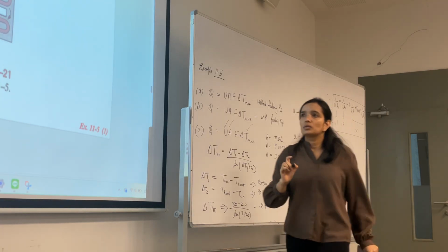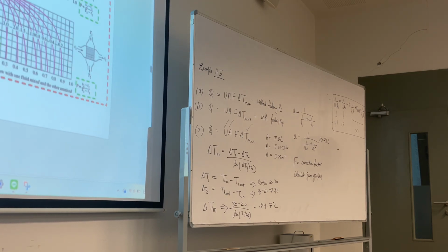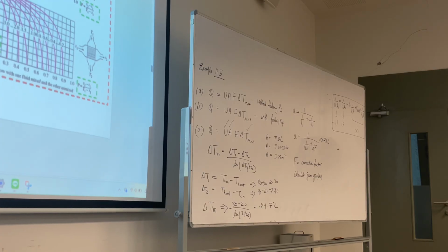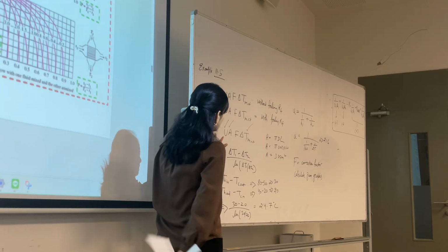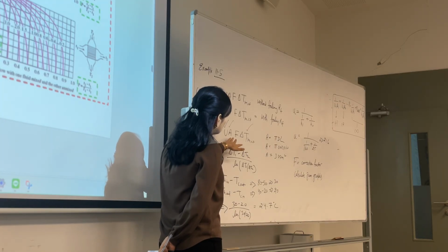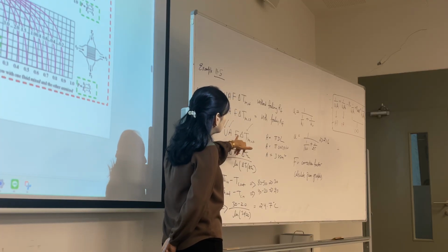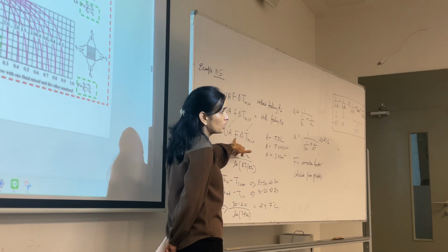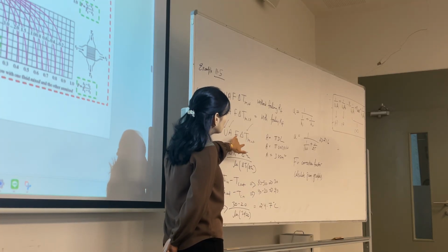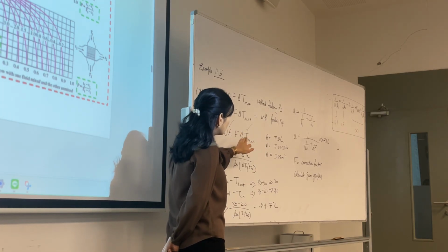How? So this question, example 11.5, is asking heat transfer rate. This is the formula for the LMTD method. U is the overall heat transfer coefficient, A is the area, F is the correction factor. We will add F when it's not a counter flow. Now it's a shell and tube. Shell and tube, so we have to include F. If it was only a counter flow, we would remove this.